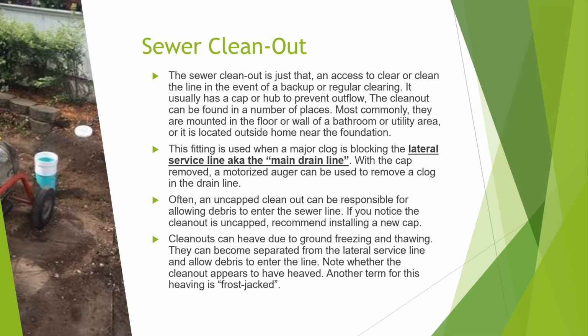Cleanouts can heave due to ground freezing and thawing. They can become separated from the lateral service line and allow debris to enter the line. Note whether the cleanout appears to have heaved. Another term for this heaving is frost-jacked.